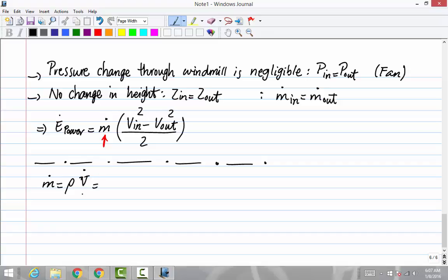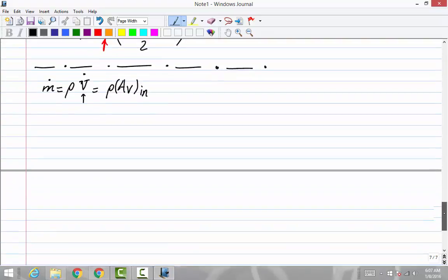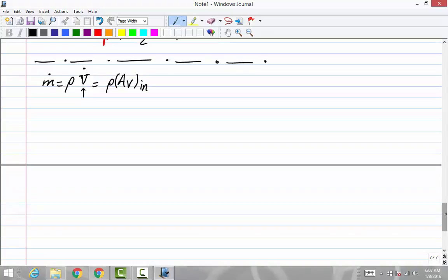And I know that the volumetric flow rate equals the cross-sectional area times the velocity, okay? And I prefer to have this at the inlet because I know that the diameter is 7. I can find the area there. And I know that the velocity is 8 meters per second, so I can just plug it in there. These numbers are straightforward. You can pick it at the outlet, but the velocity is like 7.77, so it's difficult to work with. But still, the problem is not solved because now I do not know what the density is.